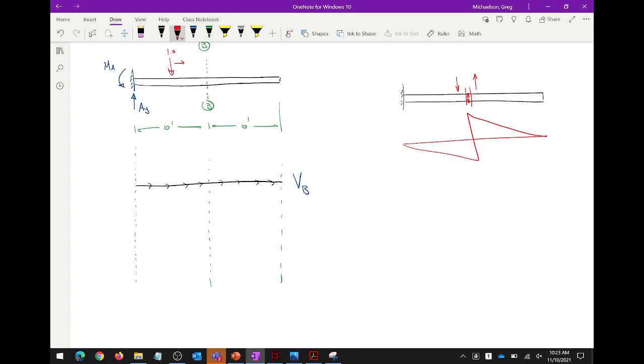If you think that this is the answer, I want you to take your hand and do that. Because what you did is you rotated this point. I didn't remove from the structure the ability to resist reactions right here when I instituted a shear release, and yet you rotated it. Now, here's the problem, okay?